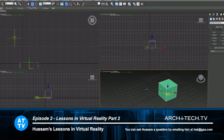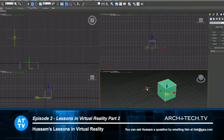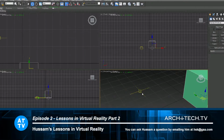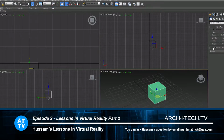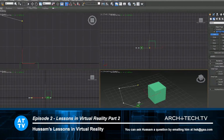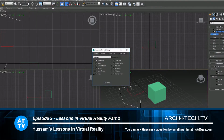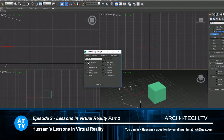The other thing is that you want to make sure what you want the snap to go to. For example, right now it's snapping in between the grid points, like you see. So if you want to change this and make it jump to the vertices of the object or the vertices of the shape like this, you have to right-click over the snap option here, and that will bring up a window that asks what you want to do with the snap.